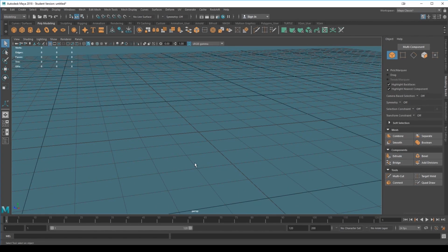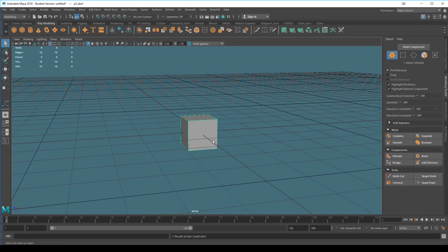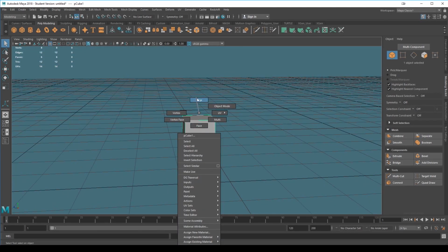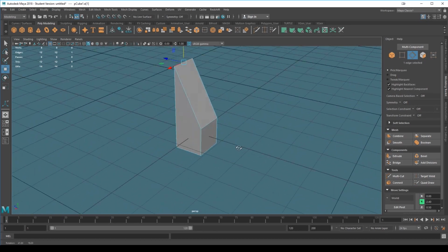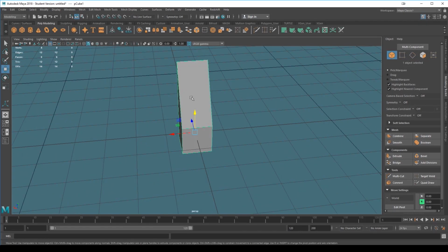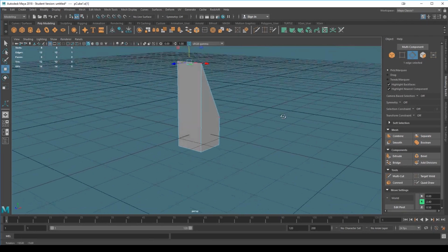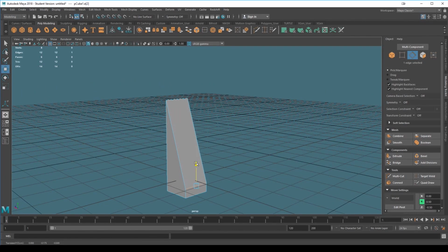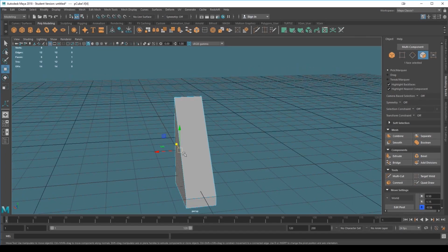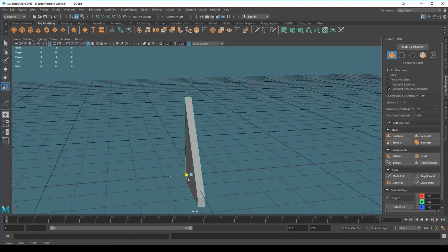It'll just be good to have a bit of a... so starting with a cube, some sort of polygon type shape. So I've just held down the right mouse, selected an edge and just dragged it up. And I might select this one and come down a fair bit. I'll go on the face mode and drag this out. And I was about to drag it in, that works just fine, but you could also just scale in object mode. Doesn't really matter.